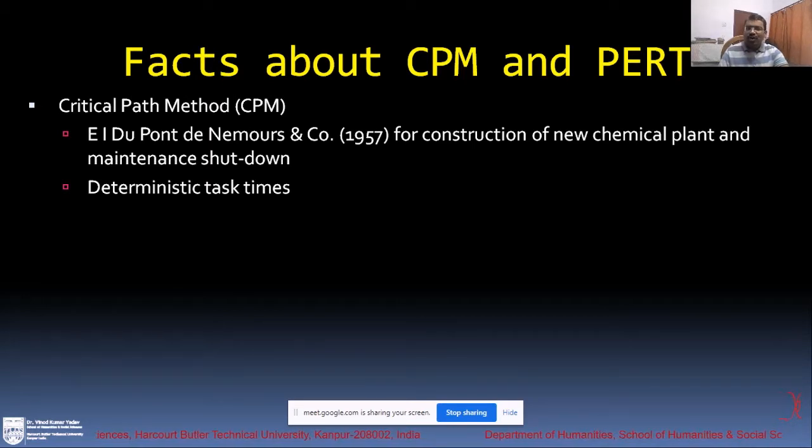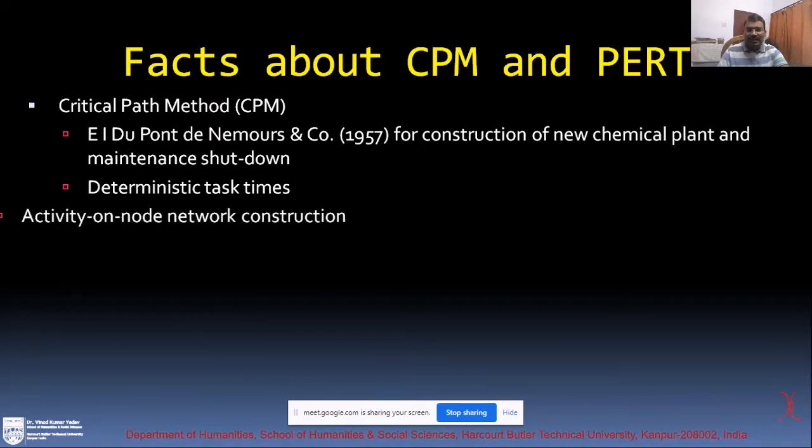So you do not have a determined time; you have the probability of an activity occurring. When you have probabilistic time, meaning you are not sure about the exact time of the activity, then you can go for the PERT method. If you have a fixed, exactly known time duration of the activity, you can go with the critical path method. So we talk about that.